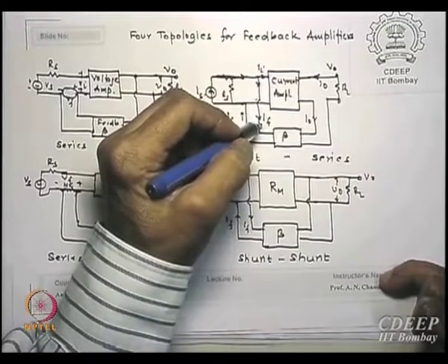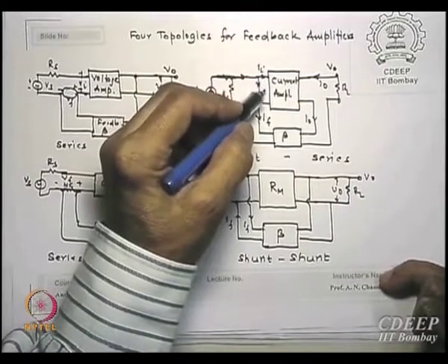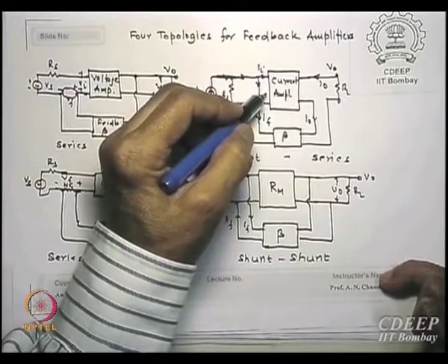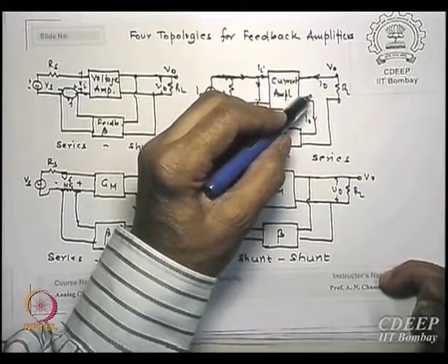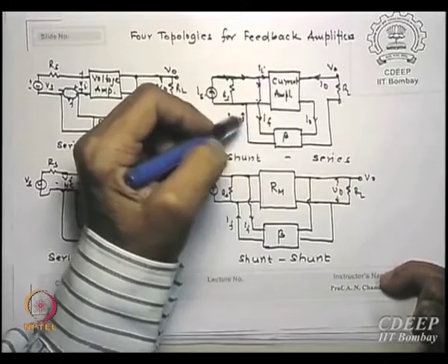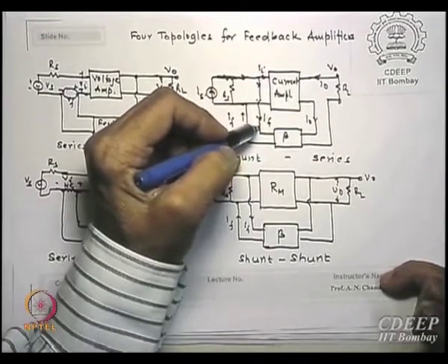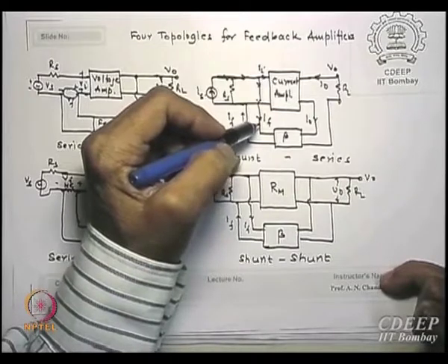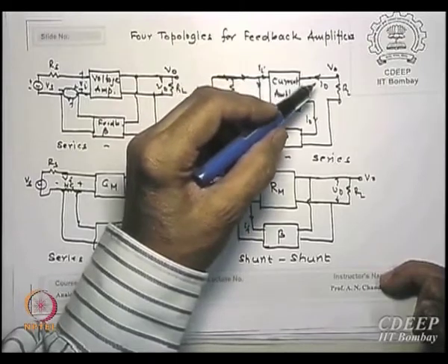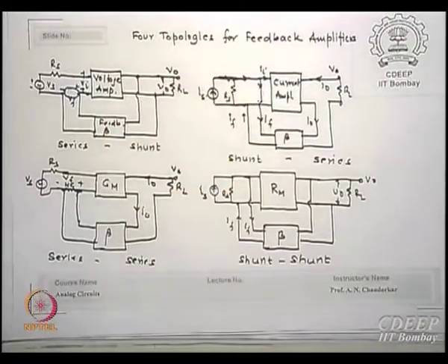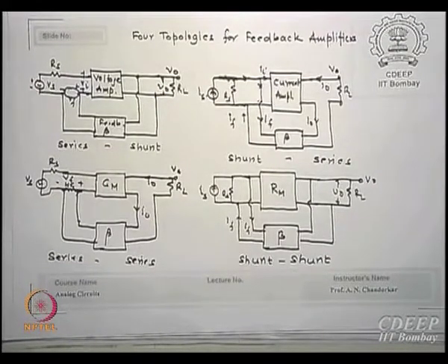That is, the feedback is larger. What does it mean? Ii is smaller. If Ii is smaller, Io is smaller. If Io is smaller, If will become smaller next time. If If reduces, Ii increases. So Io increases, and in a loop kind of way it will start reducing slowly and finally settle to a value in which Io by Ii is the gain of the amplifier and a fixed If will start flowing.